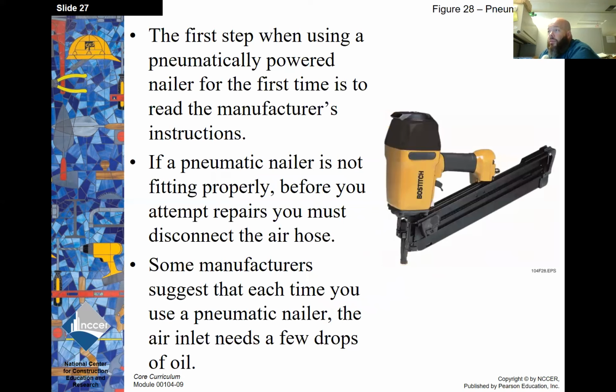A pneumatic nailer. The first step when using a pneumatically powered nailer for the first time is to read the manufacturer's instructions. If a pneumatic nailer is not firing properly, before you attempt repairs, you must disconnect the air hose. Some manufacturers recommend that each time you use a pneumatic nailer, the air inlet needs a few drops of oil.